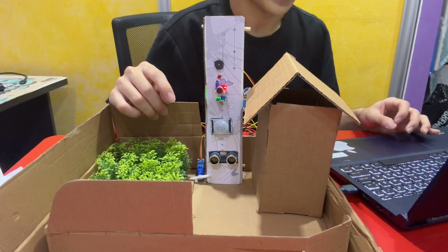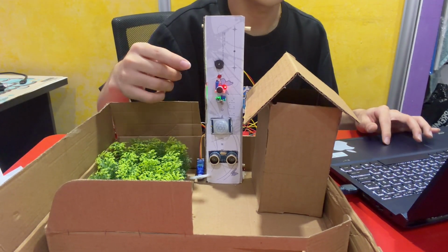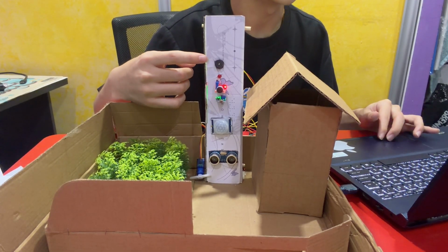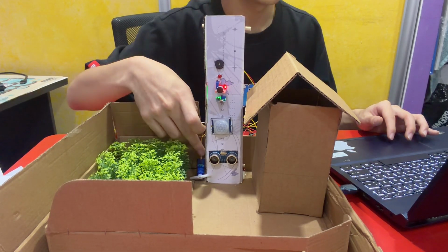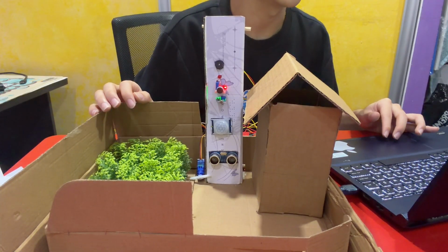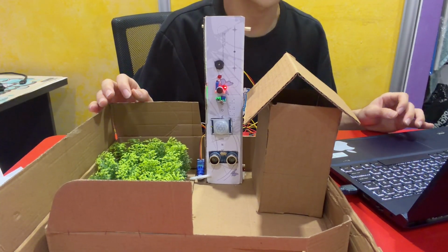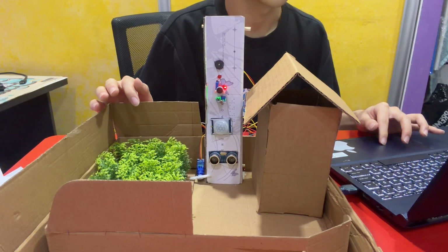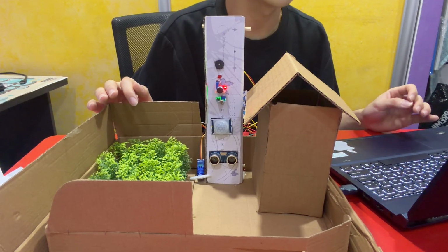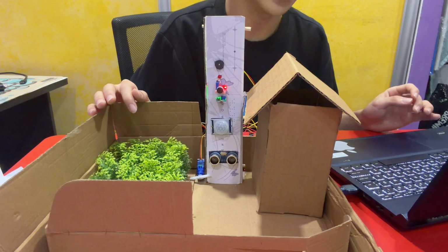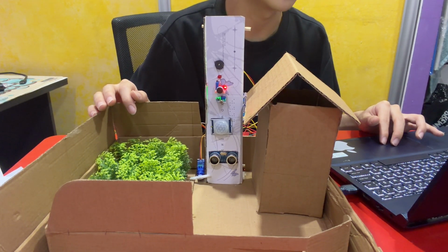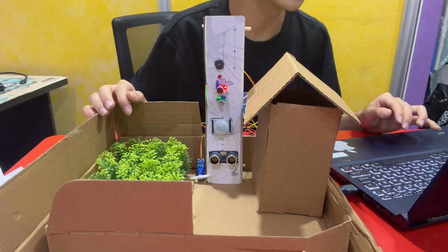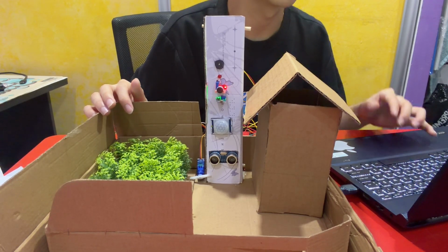For actuators, I am using 3 devices. The LED light is used as a warning light. The buzzer is used as an audible alarm. The servo motor is used to simulate a moving deterrence device, such as small scarecrow movement. The Arduino Uno is used to collect all sensor data, and the Raspberry Pi receives the data, stores it into the database, calculates the risk score, and sends a command back to Arduino.